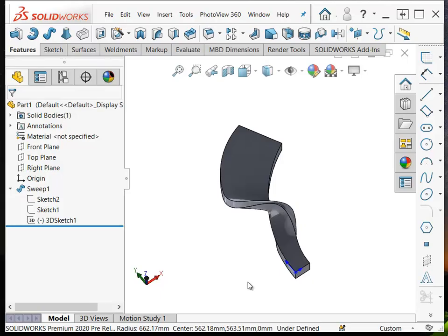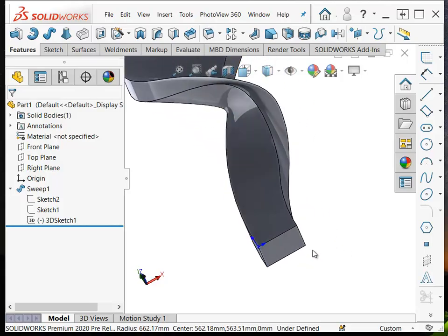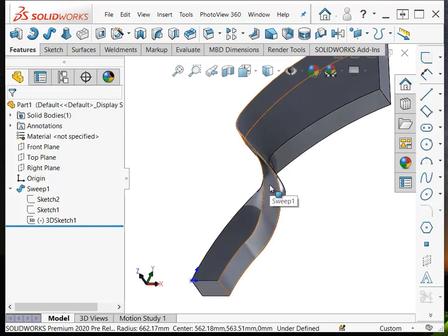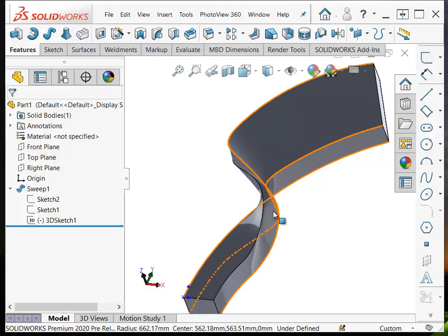So what we're doing is really driving the corner of the rectangle. If we had driven the opposite corner from the corner that's driven by the path, we could have controlled both the thickness and the width, but instead we're just controlling one dimension up here at this corner. We'll address how we deal with kind of this nasty twisting that's going on a little bit later.